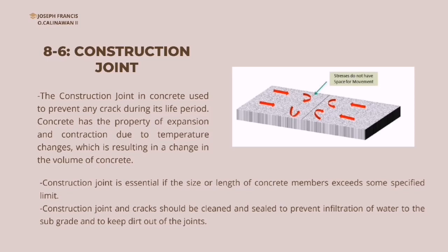Materials for such purpose include hard paving and air-blown asphalt, sometimes mixed with mineral filler, rubber asphalt, and the various rubber compounds. They are poured hot and stiff, then cooled. Others are placed cooled. They are preformed sealants made of strips of extruded neoprene compressed for insertion into the groove joints. The sealant will expand and fill the space completely.